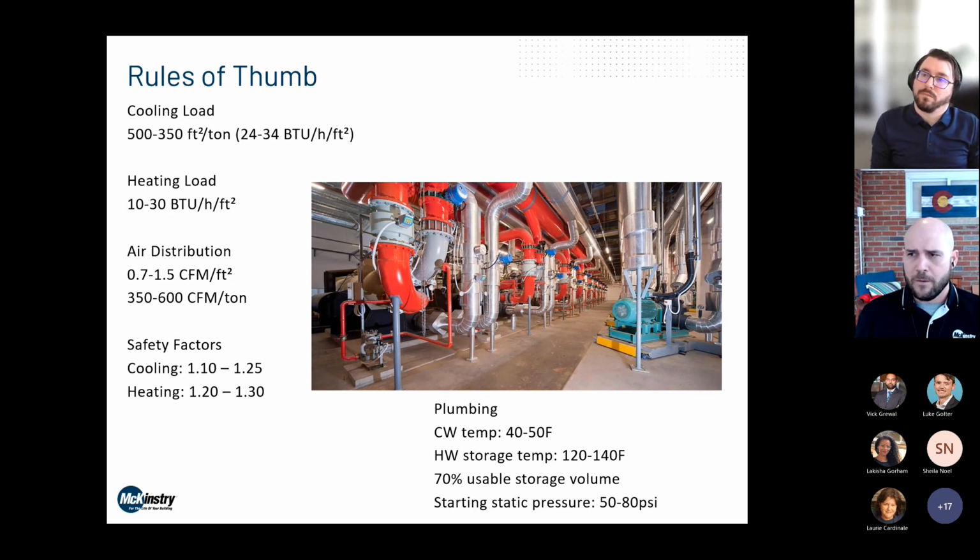We'll also mention safety factors. Cooling safety factors could be a 10% to 25% safety factor, and you certainly see them compound pretty quickly, where you add a 10% safety factor onto maybe the flow of a pump, and then you add a 10% safety factor onto the head of a pump, the pressure side of a pump, and those get multiplied together.